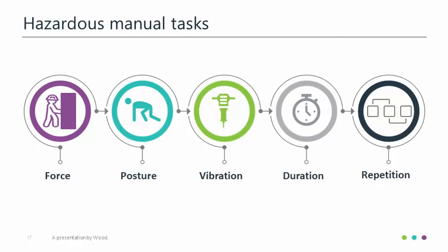Vibration. Vibration, at its most basic, is the continuous series of small, fast movements of an object either forwards or backwards, as well as side to side, about a static point. These movements or oscillations can be regular or random. The subsequent vibration energy entering the body from the part of the body in contact with the object, which is vibrating, has the potential to cause damage. It's important to recognize that vibration is recognized as a hazard under many of the states' work health and safety legislation, as well as the Australian standards.